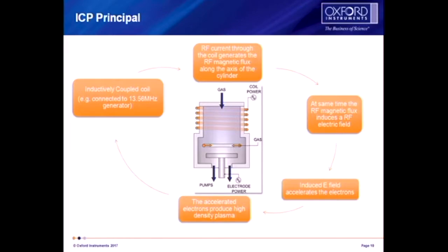There are two main advantages to producing the plasma in this way. Firstly, you get a much more uniform plasma inside the reaction chamber. When you have the two plates and you get capacitively coupled plasma, any difference in coupling between the two plates will mean that you have a different ion density inside your plasma, and this can cause things like attacking of the sidewalls, which one damages your machine, and if you attack them enough, you can end up with contamination in your films. So by using ICP CVD, it mitigates that problem. The second thing that this does is you can achieve much higher electron temperatures.